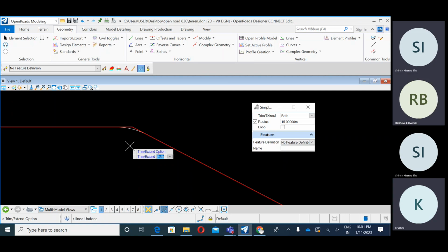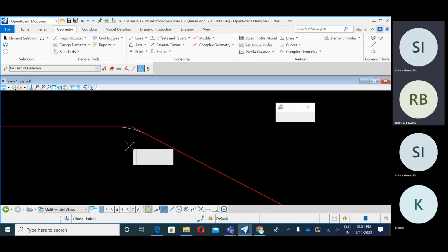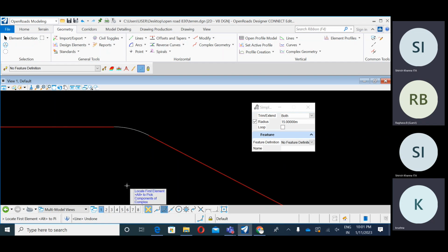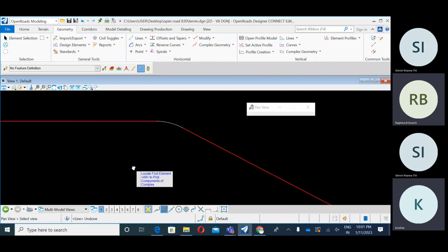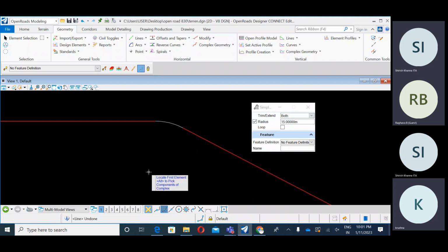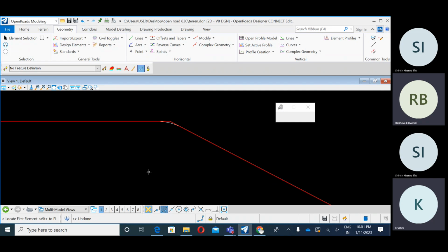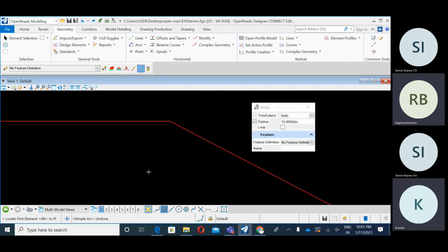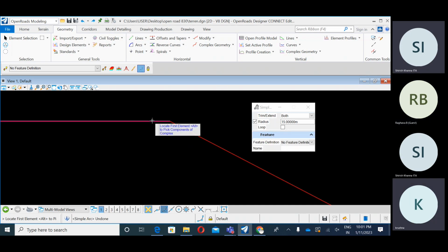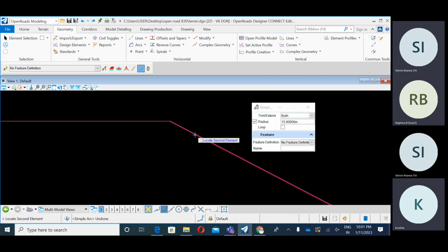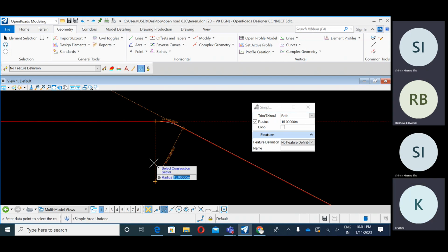It is asking for both. Yes, both. Left click to accept. Now see, it is giving you the fillet basically. By using R, we can apply the fillet. Okay, if you are not taking both, now we can change it here, or when we have accepted the value of this 15, see first, second. Now 15 we have accepted. Now left click to accept.